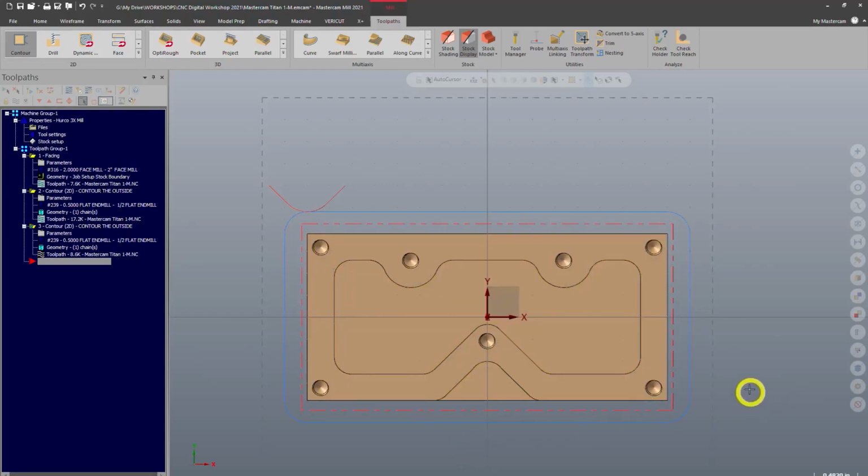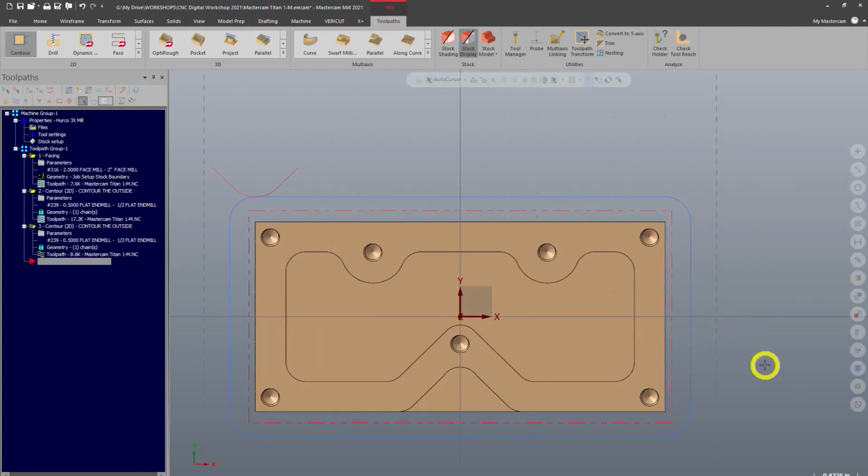So programmers and developers have come up with a new type of toolpath known by various names. In Mastercam, it's called dynamic milling. In Fusion 360, it's called adaptive roughing. So it's a really useful toolpath, and it has a lot of control. And what it does is it peels away material. So even when you get into a corner, you're still maintaining a constant tool engagement. So you're not going to overload your tool, potentially breaking the tool, and it generally leads to a bit longer tool life, which is really useful.